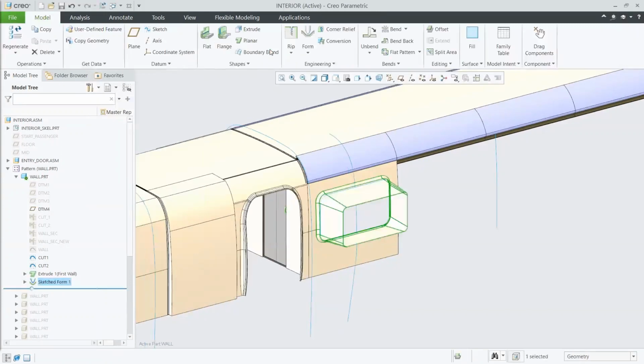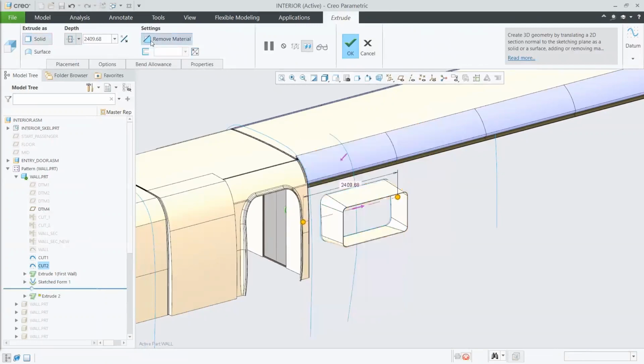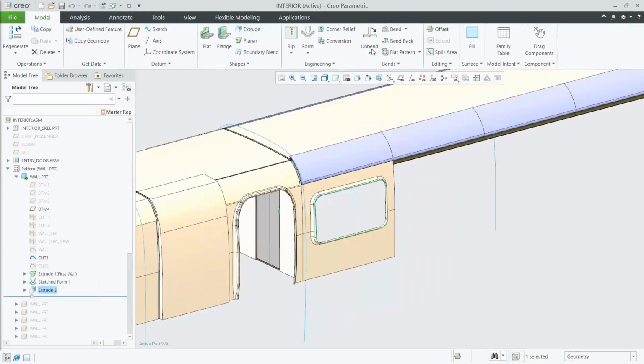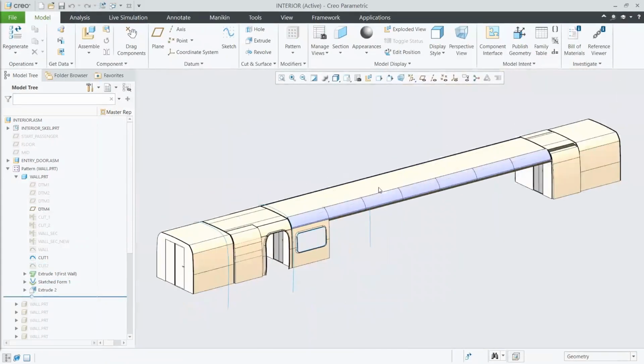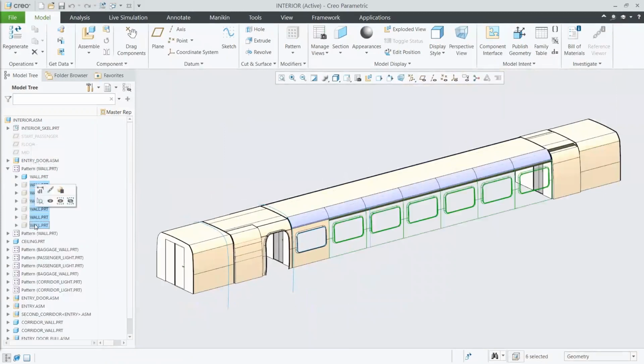And we're just giving it a taper, rounding off some of the hard edges. And again, it comes out a bit further than we need to. We're using that curve that we brought in to understand exactly how far out we want it to go, and copy geometry for that. We're still letting the master geometry control all of it, but I get to use it here inside my work. And I don't have to have the whole train. If I'm just working on the interior, I don't have to load up all that geometry.